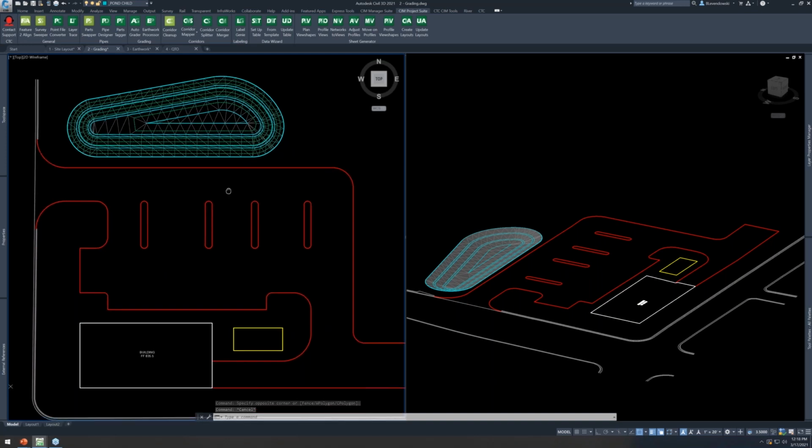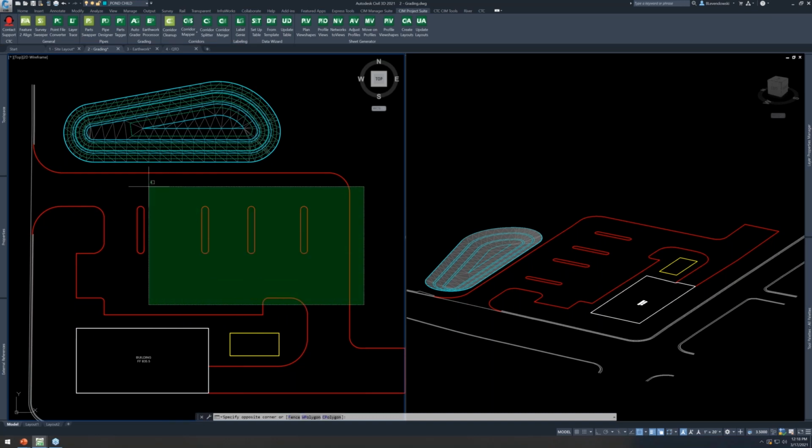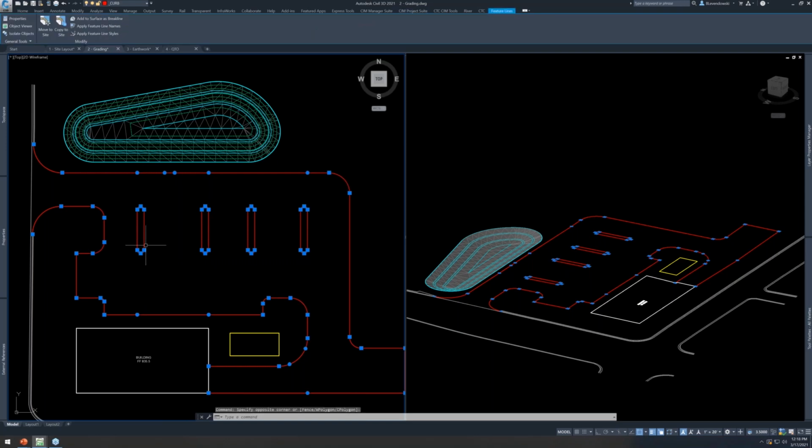And I also want to incorporate another piece of grading out parking lots here. Oftentimes, managing all the elevations across your parking lot becomes quite tedious. And so I like to, at least for a conceptual portion, preliminary grading of my parking lot, take advantage of a grid surface. That's a surface that allows us to read elevations from it, to assign elevations to curb islands, to this perimeter curb, and so on.